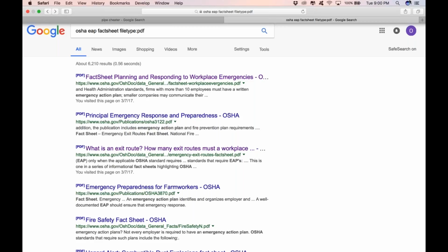Okay, as warranted by the project, the employer shall provide a trained and equipped firefighting organization, so a fire brigade or an emergency response team, either one, right? And they have to be adequately trained and selected. A temporary or permanent water supply with sufficient volume, duration, and pressure. So it could be fire hydrants, it could be out of a lake or a pond with compressors and generators. So just depending on what it wanted to be sufficient and necessary for our facility.